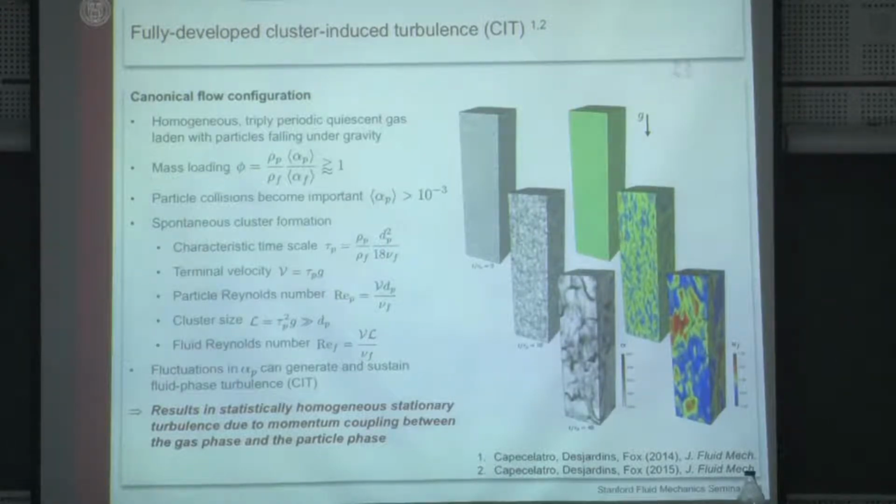So now we're looking at particles settling down due to gravity and fluid that is maintained at 0 velocity overall through global forcing, through essentially a vertical pressure gradient. All right? That doesn't mean that the fluid is not allowed to move. The fluid evolves in any way it wants. It's just going to experience a forcing term that will prevent its mean from evolving away from 0.